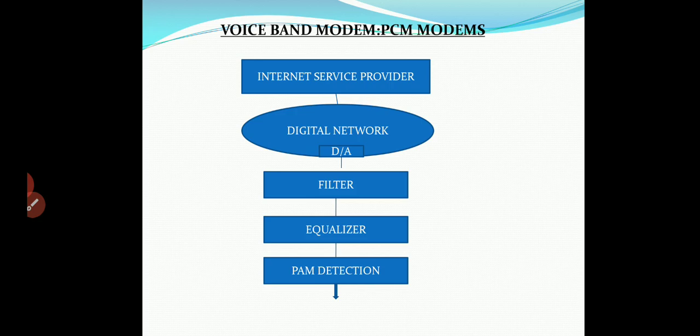In the early 1990s, voice band modem technology improved dramatically. It became standard with ITU's recommendation. There are two primary factors in the rapid advance of voice band modem performance. First is the availability of economical DSP technology for echo cancelling. Second is the improved quality of the network, with lower noise and distortion from the all-digital implementation.